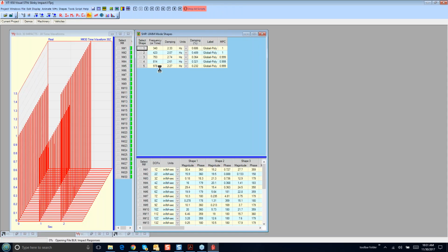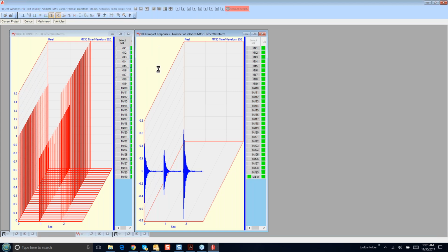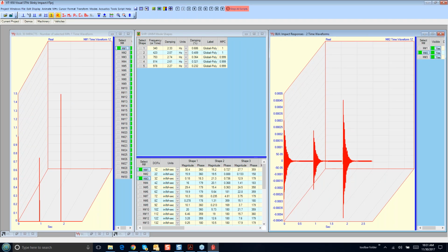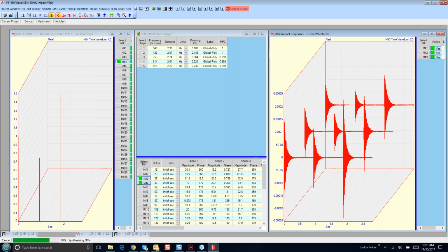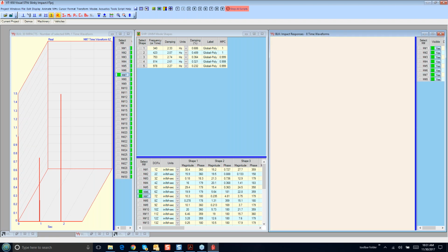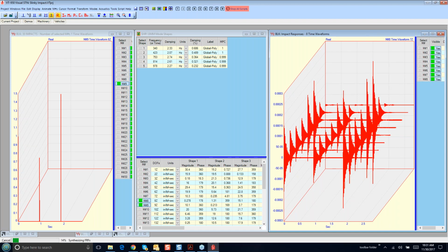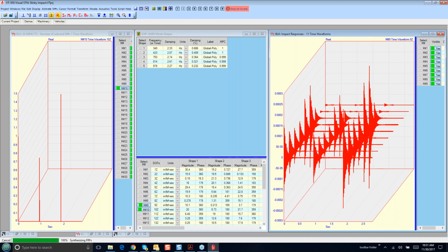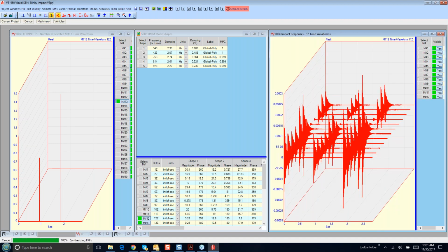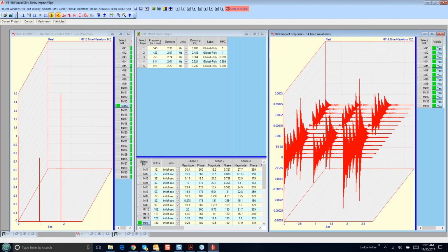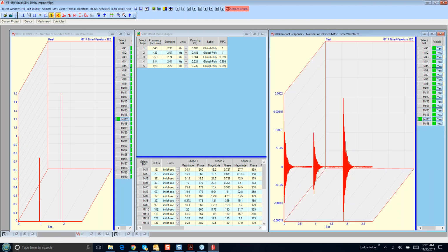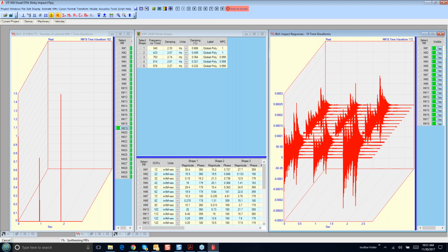Now in real life the impacts wouldn't all be the same, but it doesn't matter because this is another input-output model where we get the outputs due to the impacts. We could have randomized the impacts, but we're using the same ones here. So now the MIMO calculations are going on in the background, and we're computing the response of the flat plate to 3 impacts at each of the points. And we'll see here in a minute, when we post-process this data, how the Slinky impact test actually proceeds.